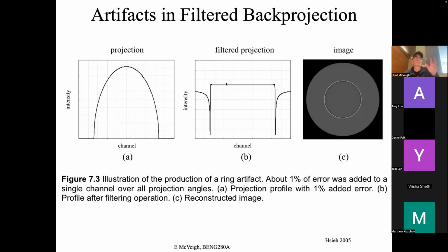And so that very small percentage change gives you this ring artifact. You can usually, if you look carefully enough, see them. Now, if the signal's really big, the ring can be drowned out by the other signal. But here the signal's totally uniform, so it's sort of the worst case scenario for seeing that.